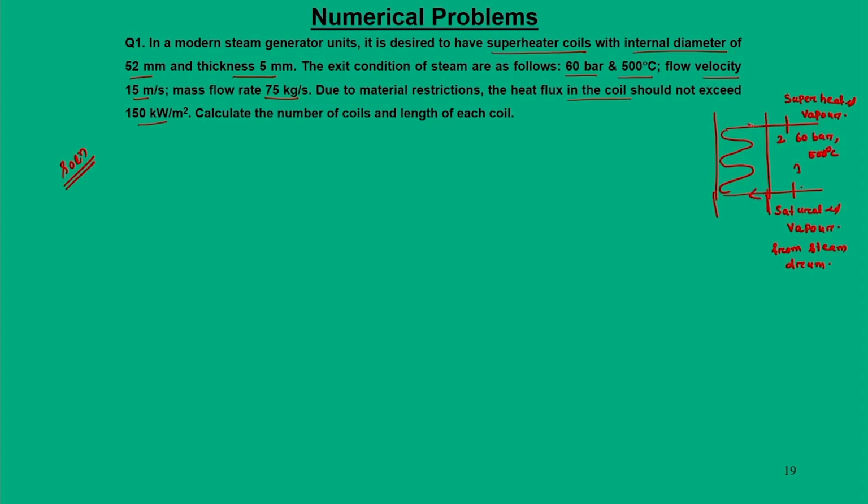It enters through these tubes in a continuous manner, and on this side we have flue gases of mg dot, Tg1, and the flue gases leave with mg dot and Tg2. That means heat is taken from the flue gases to this steam, and essentially it is a convective type of superheating, where we can draw this curve.